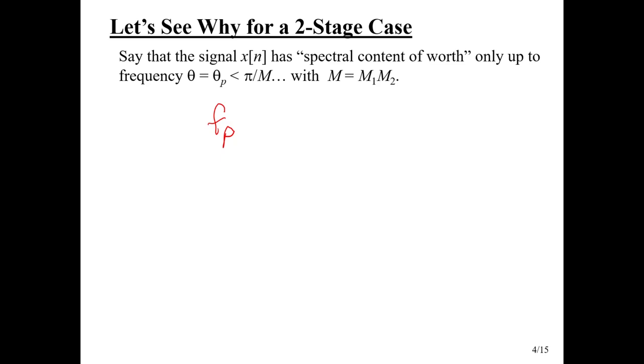So we have an audio signal that we care about things up to that highest audio frequency. I say 18 because that's the number that I use in an example later, just to make some numbers work nicely. But for us, it might be 20 kilohertz. And then whatever our original sampling rate is, that's what would map that to that theta sub p. Okay, so that's the idea.